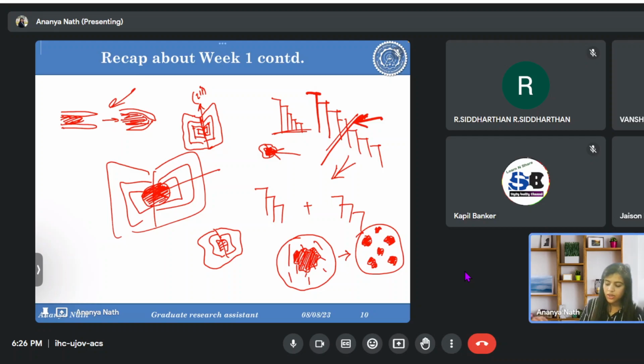TPRE is not a theory. TPRE is twin plane re-entrant edge. The edge or the direction through which this starts is called the twin plane re-entrant edge. Wherever that TPRE is found, that is a stable site, so from there the growth will start. And using modifiers, we can restrict that growth. It's not another theory, it's a similar thing; we are just adding modifiers to change the growth site, as simple as that. Okay, I understood.